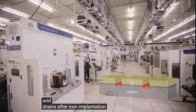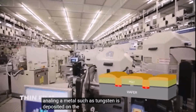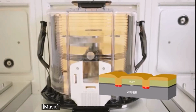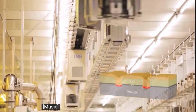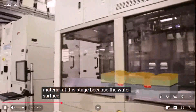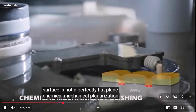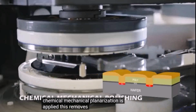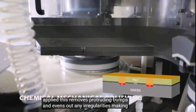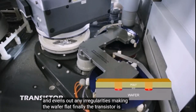After ion implantation and annealing, a metal such as tungsten is deposited on the wafer as a contact material. At this stage, because the wafer's surface is not a perfectly flat plane, chemical-mechanical planarization is applied. This removes protruding bumps and evens out any irregularities, making the wafer flat. Finally, the transistor is complete.